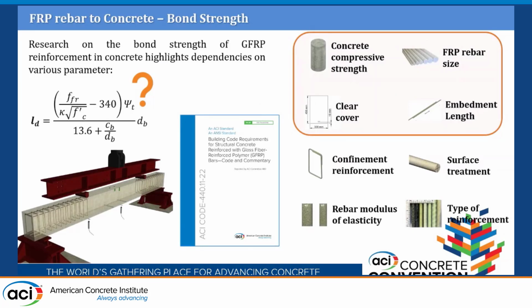The main objective of this first phase of the project was to evaluate the bond strength, the development length and the lap-spliced length of GFRP rebars. This is because the current equations based on literature review could apparently be conservative, others say it could be over-conservative, others even say it is reliable enough to keep working with. Based on this discrepancy between different research, we decided, in this first stage, to address the equation with the current parameters included in that equation.